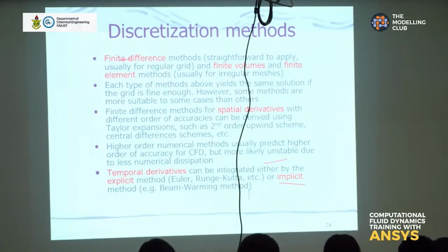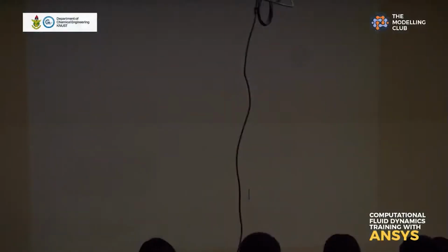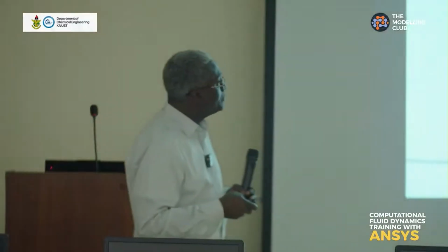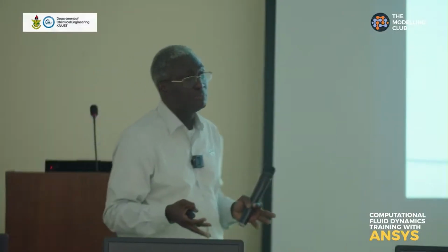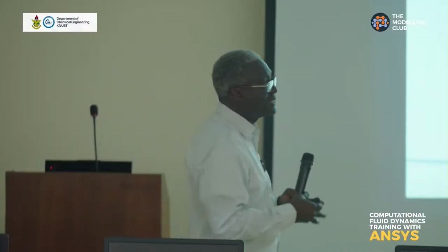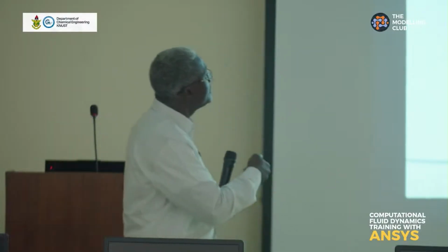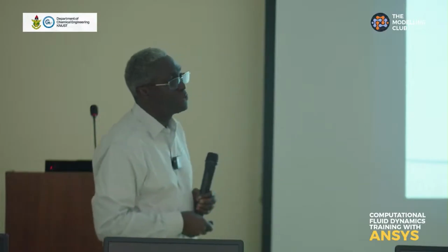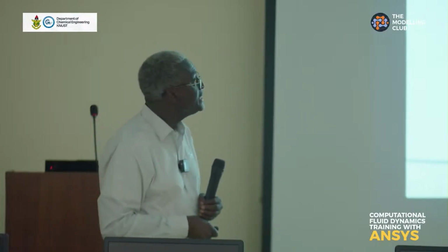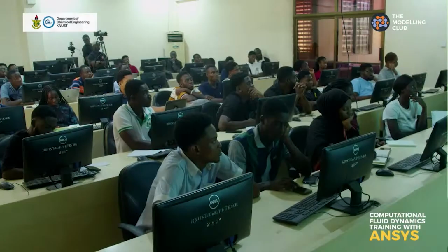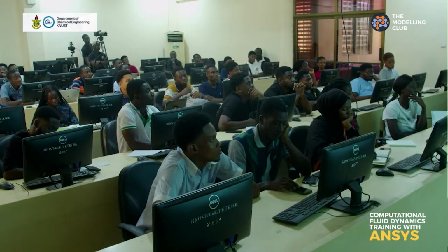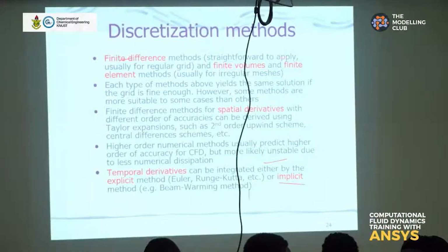What is the advantage of using one over the other? It all depends on the complexity of your problem. If it's simple geometry, then finite difference methods would be appropriate. If it's a more complicated structure, then it's best to use the finite volume or the finite element method.